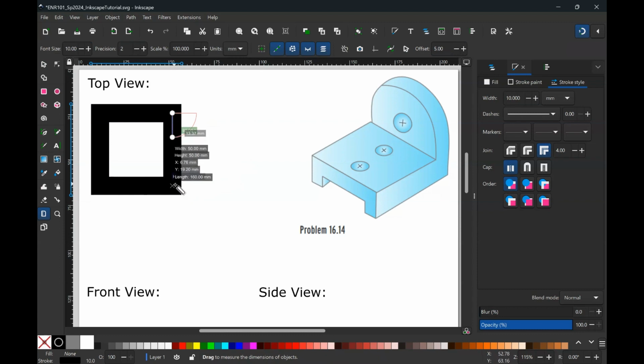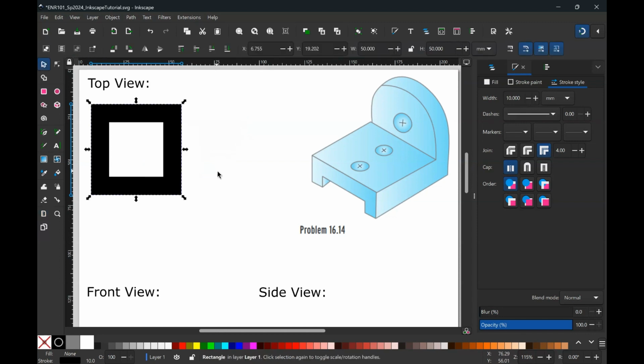What I actually want to be representing would be the center point of this line, which, if I was to anchor towards the individual corners there, I would see is only 40 millimeters. So essentially the width minus the line width, or the stroke width. So one thing I have to do here in Inkscape, and in a lot of drafting programs, is to be mindful of that and to set my units accordingly.